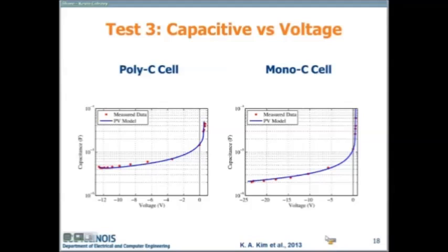And so this is done mostly through model fitting. And I'm leaving out all the parameters because it's kind of tedious. But you can, of course, read the paper if you want. And then the same thing is done for the monocell. Notice here we actually don't see the avalanche capacitance become dominant. I believe it's just we didn't go far enough into the reverse bias region, mostly due to thermal limitations.